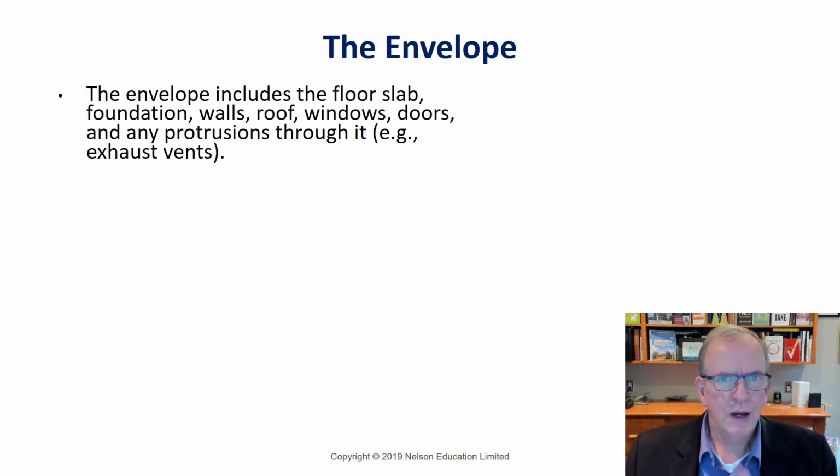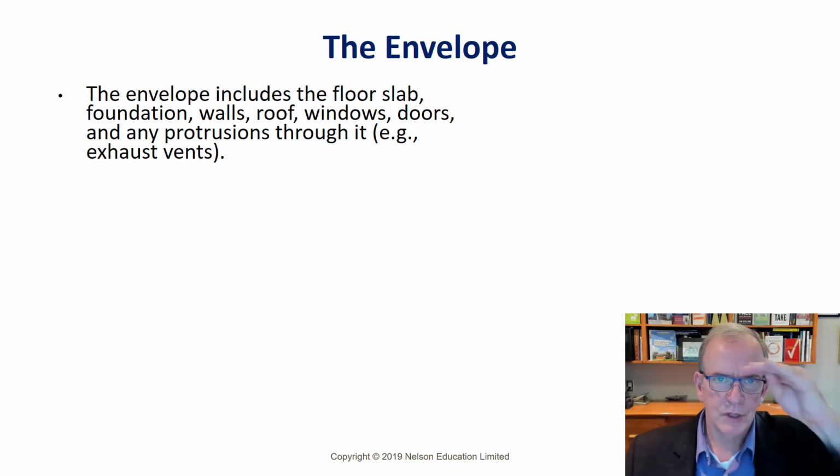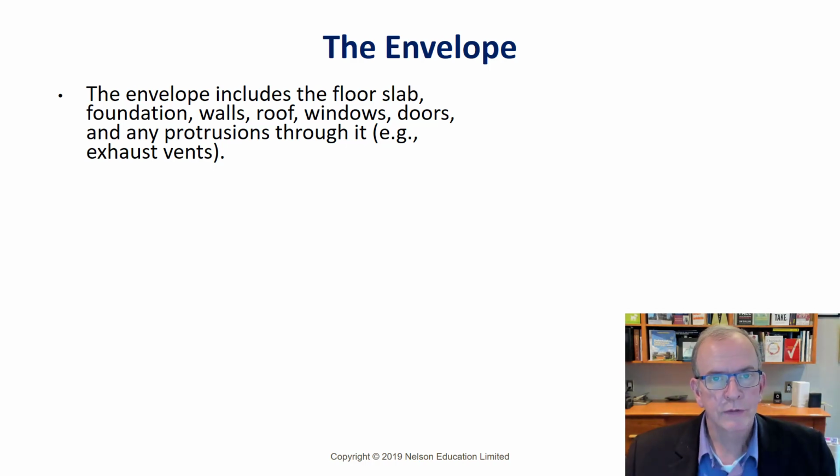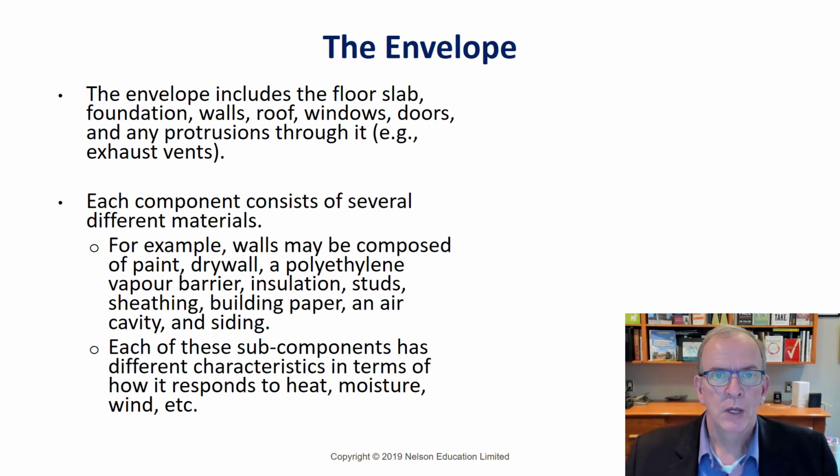That would be kind of how we think about the envelope, and that's how we seal up our residential structures. So if the garage, for example, is not heated, well, that would be unconditioned space. So we would try to have a tight envelope between the garage and the rest of the house. That would include the ceiling of the garage and the interior walls of the garage as well, so that we don't have a lot of heat loss from our house or our building.